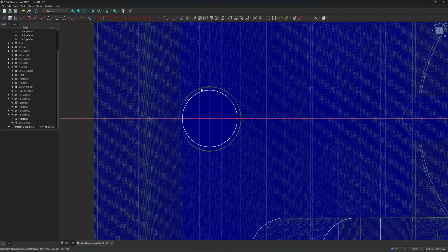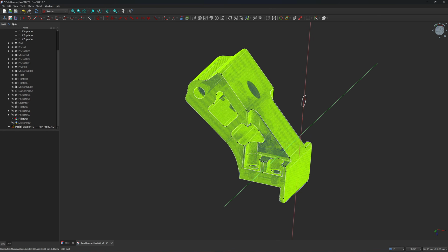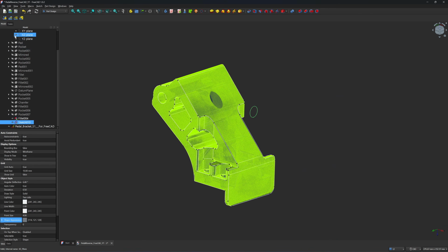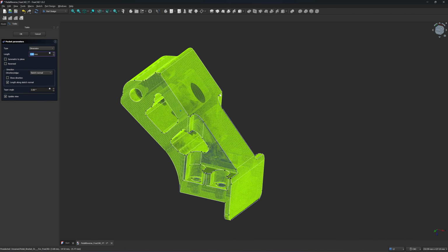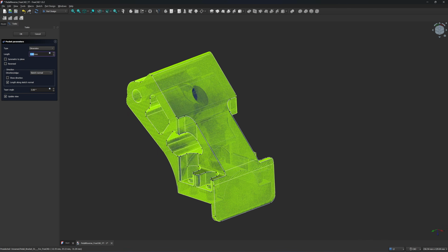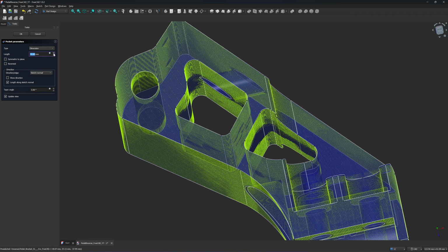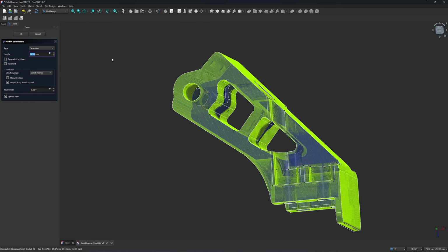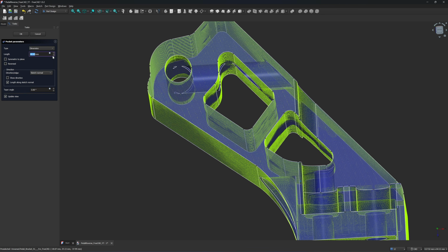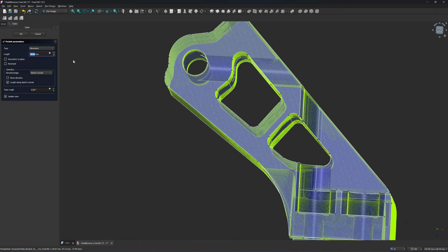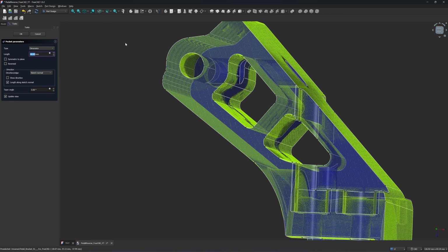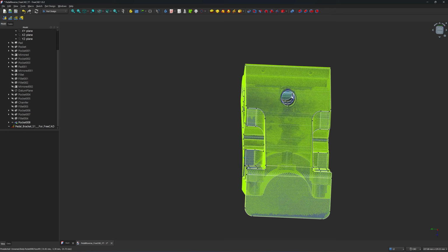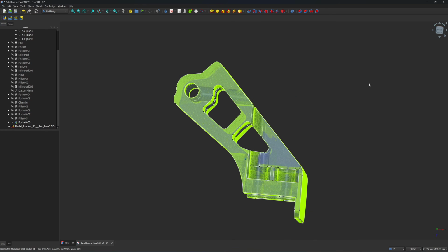The pass-through hole will be larger. I think it's 9 millimeter. Next, I'm going to click on close, pocket cut. You won't see anything because the distance will be like 50. Add a number. Okay, now it's 62. 68 is too much. Okay, 66 millimeter. So now the hole passes from here through here.